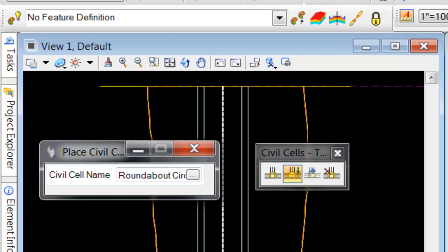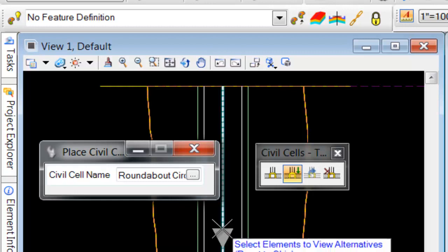If he moved up to the top line there, he'll have that same arrow that way, so we could flip it that direction. So what could happen to you is if you're going to place a driveway that's got radius points on it, it might put the radius points on the other side of the line where you intended it to be. So if you pick that center line again and flip the arrow, then it'll flip it to the other side. Okay, so sometimes you really have to mess with them to get them to be exactly right, but that's what those allow you to do.